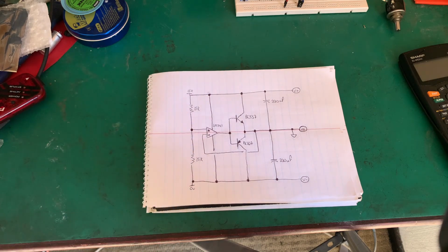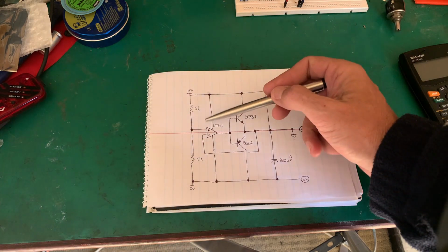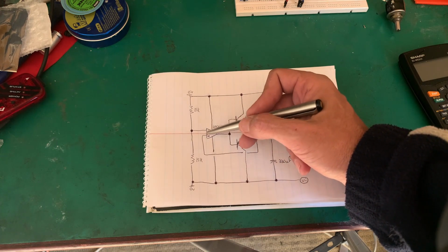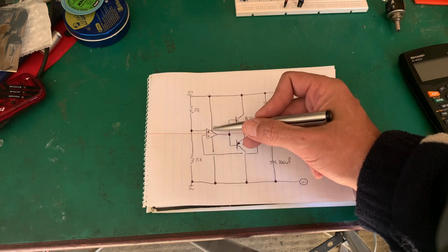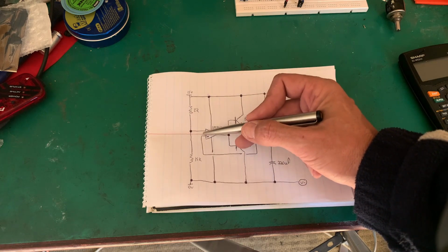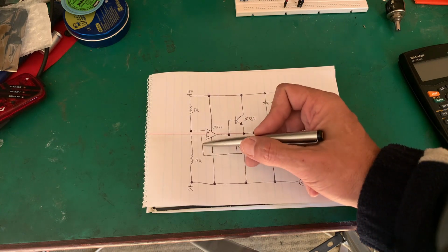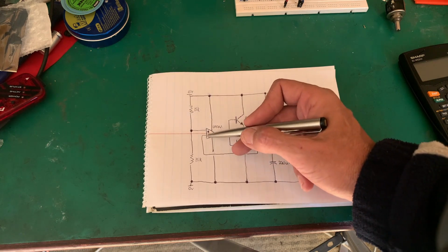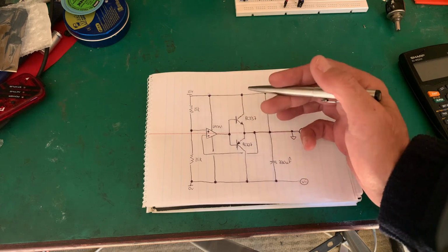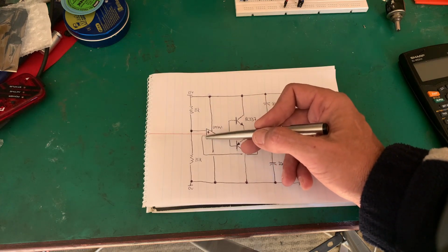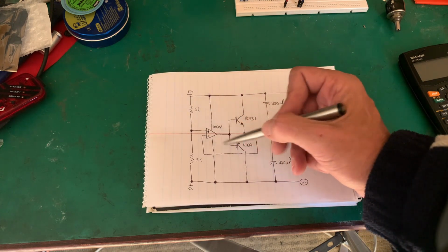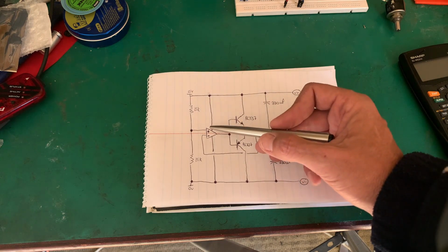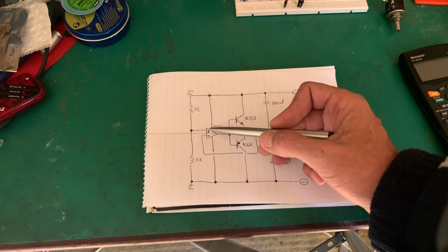So this looks a bit complex. It's not really. We understand the action of the op-amp. The op-amp is doing whatever it can to make these two the same. The output is doing whatever it can to make these two the same. Notice no resistors in that path, so no feedback. So it's almost like a buffer with a gain of 1. In other words, there is no gain. So the output will follow the input. The other important thing to note, what did we say?